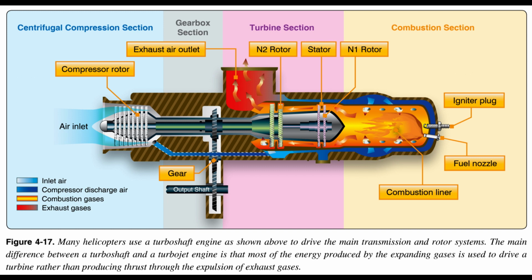If the airflow through the compressor is disturbed, a condition called surge, or compressor stall, may take effect. This phenomenon is a periodic stalling of the compressor blades. When this occurs, the pressure at the compressor is reduced and the combustion pressure may cause reverse flow into the compressor output. As the airflow through the compressor is reduced, the air pressure then increases, temporarily correcting the condition until it occurs again.